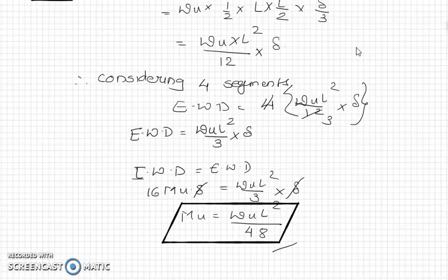Okay, so this is the amount of movement at which a fixed square slab will collapse or fail. So this is again the derivation for movement or yield movement when the slab is square and has fixed edges. So there are 2 yield lines developed, positive and negative yield lines. So again we have followed the same procedure of writing equation for internal work done and external work done and simply equating it.